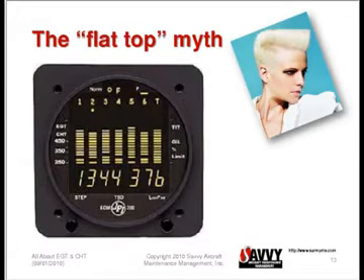Let me try to dispel what I call the Flattop myth. The Flattop myth is that in a properly running, well-balanced engine, we want to see all of the EGTs the same. We want to see our bar graph indication have a nice flat top to it, and we really want to minimize the differences between the different EGTs.